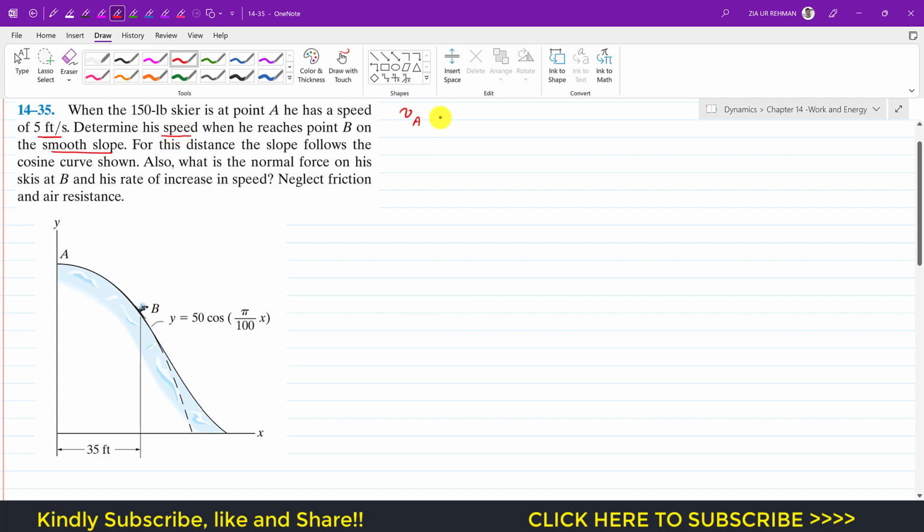So VA is given, that is 5 feet per second, and we have to find the velocity at point B, and the point B is located at a distance of 35 feet from this origin in the horizontal direction. It is said that for this distance the slope follows the cosine curve. Also, what is the normal force on his skis at B? So we have to find N_B as well, and his rate of increase in speed. So we have to find the tangential acceleration at point B as well. The rate of increase in speed is always the tangential acceleration. And it is said to neglect friction and air resistance.